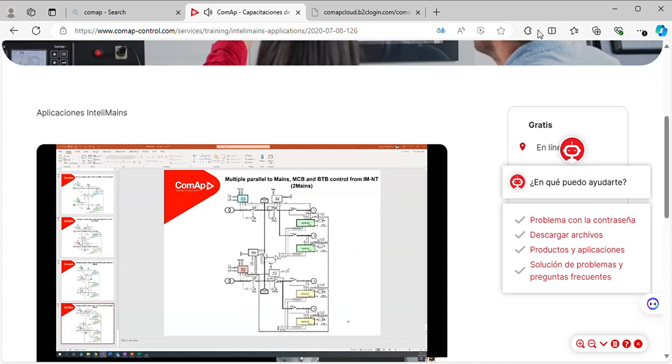So the first genset started because there is a grid failure. So a valid grid failure happens. The second genset is also starting. It is feeding up the load. The second one would start and synchronize with the first one. So now everything will happen automatically. I do not have to touch or control the breakers.